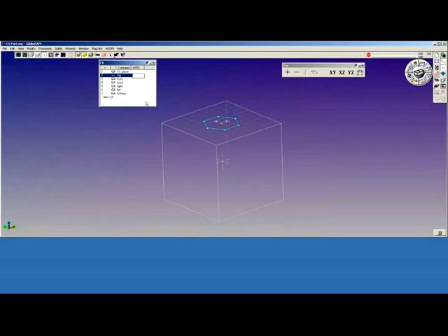And that's the numbering convention. So if I want this second coordinate system to be a G56, I would type in the number 3. This would force a G56 for this particular coordinate system. And my post processor would generate a G56 when it machined on the top of the part.